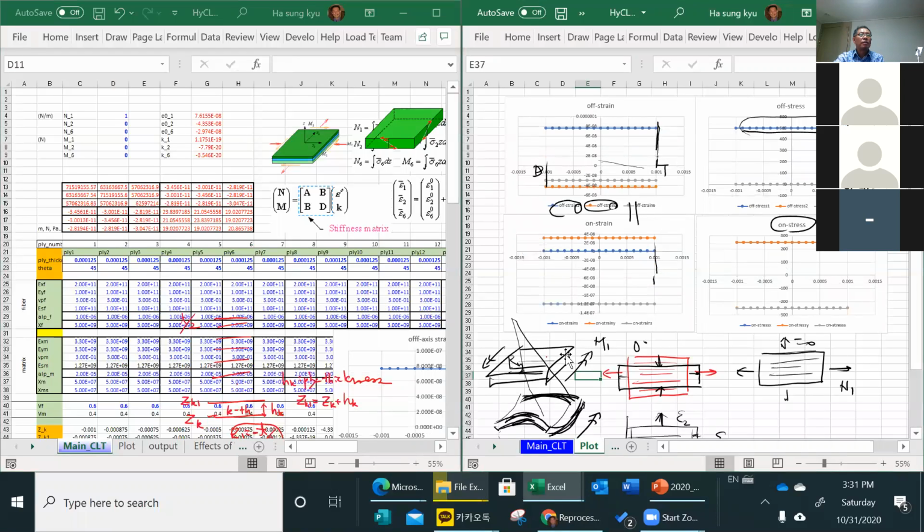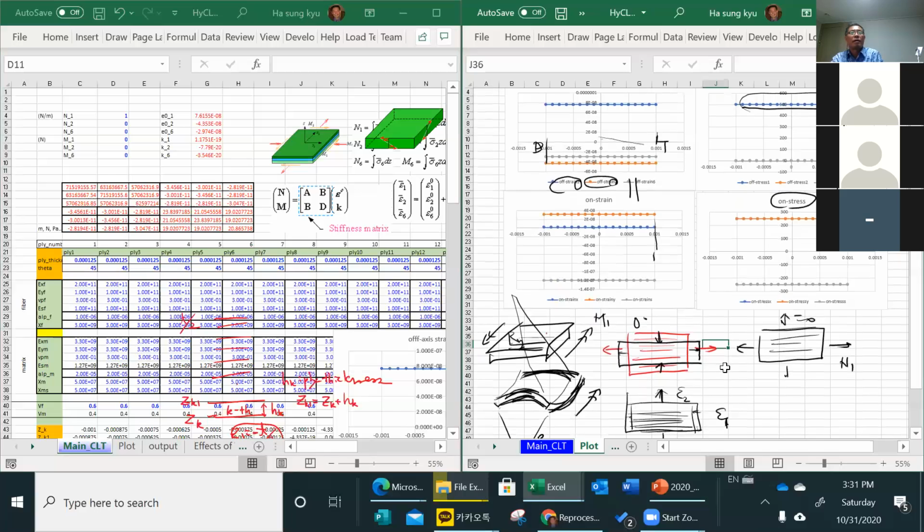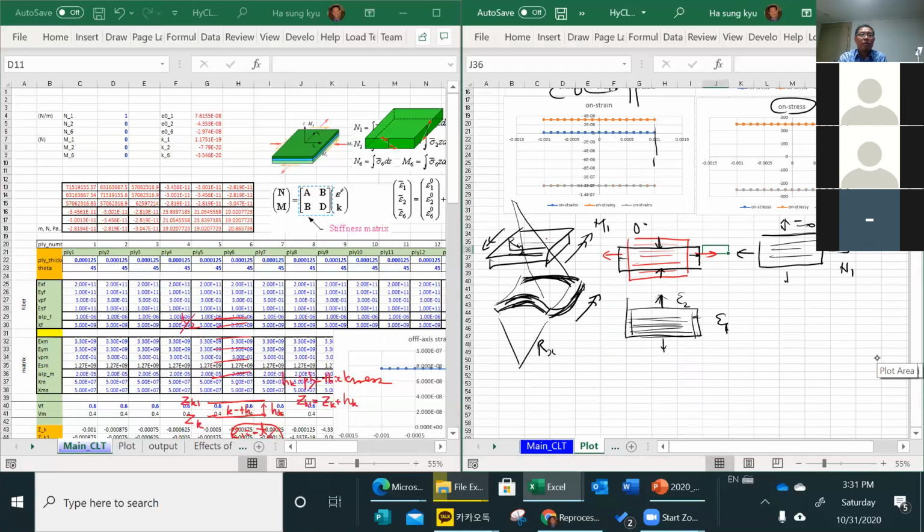What's happening here, importantly, is that we have just a 45 and apply load, right? Then this is going to extend, and at the same time, of course, shrink, but importantly, we're going to have a shear strain. The angle will change, shear strain, because 45 is not balanced.